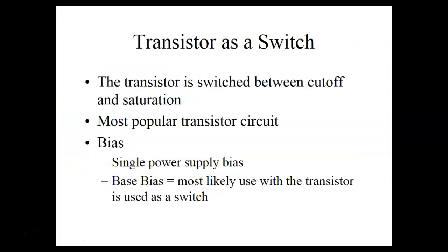The problem we have with FETs, field effect transistors, is that they are susceptible to damage by static discharges. Anybody that works with FETs should use static bands or not handle them a lot. Bipolar transistors use a current to control the current. So odds are you can't hurt these things that way. You're not going to discharge into them, because static electricity does not produce a current flow, right?